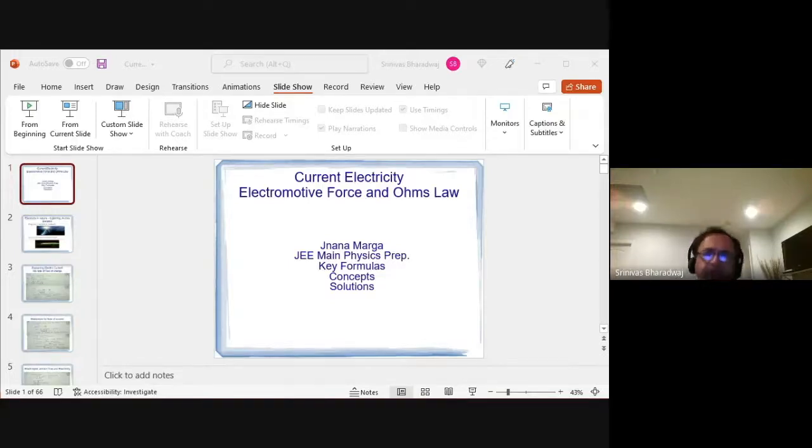Now, Kirchhoff's laws, there are two laws. In any closed loop, you go once around the loop, you will end up with zero, right? Any closed path of the circuit, from the starting point you go one full circle, you end up with zero. And at any junction, the current coming in will equal the current coming out, because there's no charge stored at any place in a circuit. Charge just keeps circulating, right? So that is the basic idea in Kirchhoff's: sigma I equals zero, the junction law, and sigma V equals zero, the loop rule.